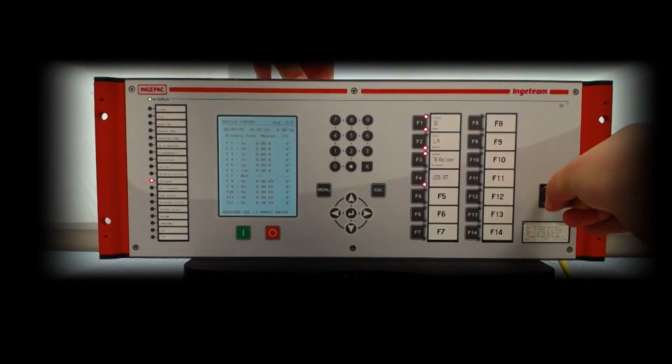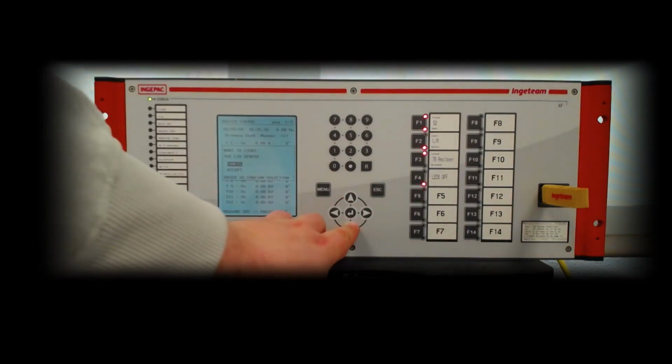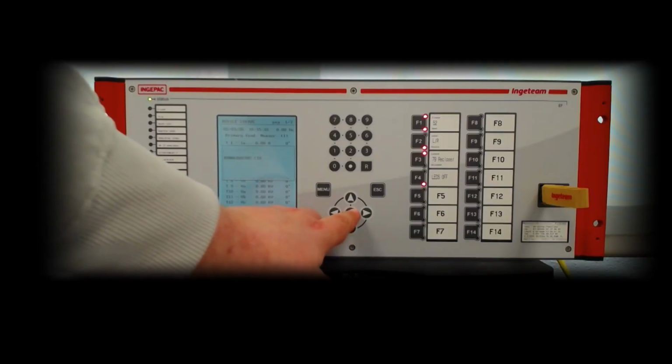In addition to downloading the backup files of the device, we may also upload new CID configurations to an IED through its USB port. To do that, we will need to insert a USB stick which only has a CID file in the root folder. The IED will detect the USB and first download the backup files to the USB. When the download is finished, the IED will ask the user for confirmation to start the CID update process.